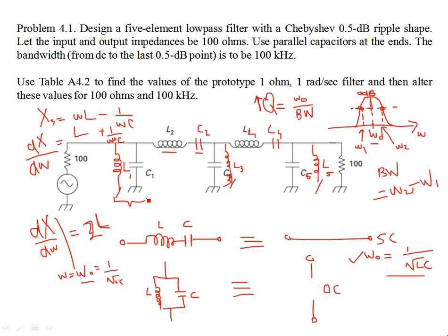Okay. So due to this reason, whatever is the value of the inductor, you have to divide that by 2. You have to divide that by 2 because the inductor and capacitance are going to contribute equally, and at resonance, the inductor or capacitor is going to have reactance which is going to fall off with respect to the frequency on either side of omega naught at twice the rate of that inductor or capacitor. Okay, so you have to divide that by 2.